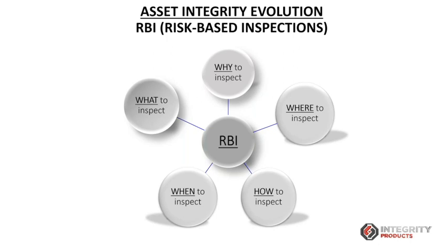That is based on certain set intervals in the inspection program. And how to inspect, that is the question. We have different measures in place. We can use water detectors. We can use non-destructive examinations. Which one do we need to use where? That is how we can make our inspection programs smarter through the use of RBI.